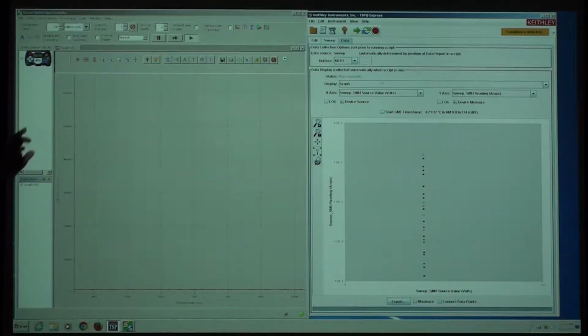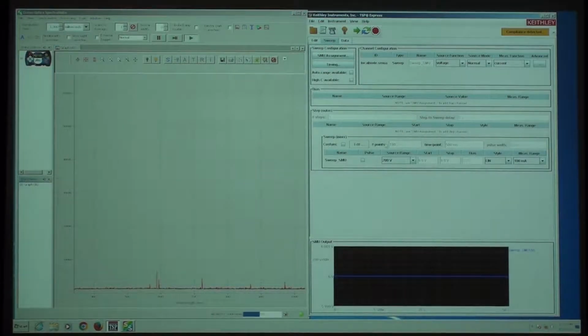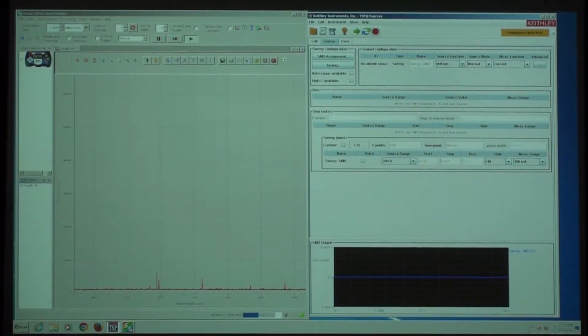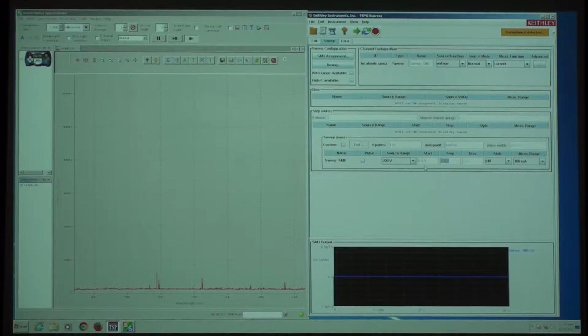So the spot is holding something like 1 microsecond. Otherwise, it will be like when it starts lasing. This is a huge integration time. While he's setting it, one of the big problems with lasers is it is extremely efficient in converting light, but you have to cross a very big threshold. So there is a lot of heat dissipation. If you're not careful, you can easily burn it. So first we want to do an IV curve from low to maybe 6-7 volts.